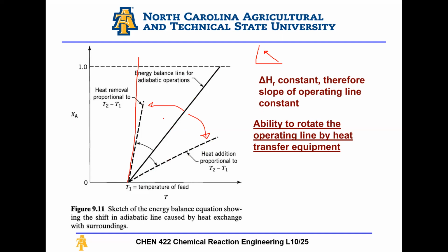However, in oil and gas, for example, where these types of scenarios are not very common, we operate isothermally so that we have the maximum possible conversion by either cooling. So for example, with water gas shift, steam methane reforming, all of these reactions, you try to operate isothermally by either removing heat or adding heat. This way, you don't really need to worry about variability, and it allows you to have better control of your product, especially if you have a large plant.